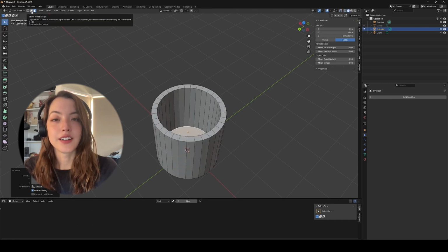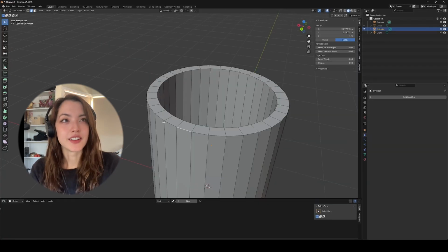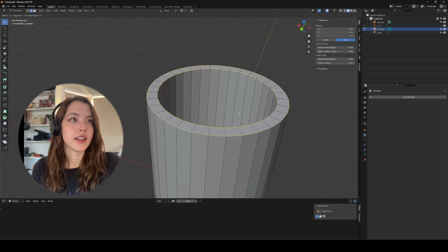We're going to click on the edge select. We want to select the edges of these entire loops. So hold down Alt, double click, then keep Alt selected, hold down Shift as well, and click on the next loop over. We're going to add a bevel to these, so press Ctrl B and just drag this out a little bit. And remember, you can use the mouse wheel to reduce the number of loops.